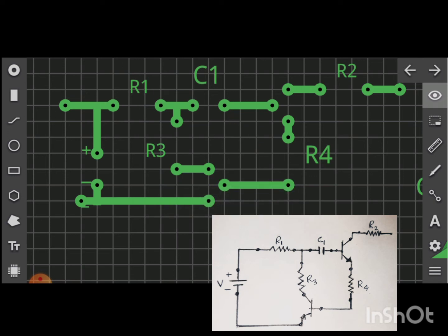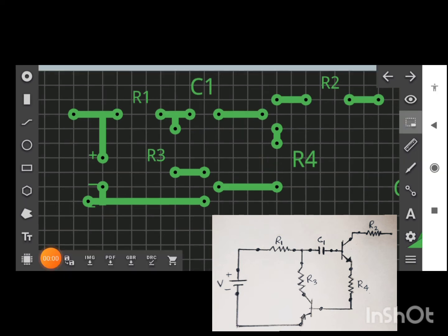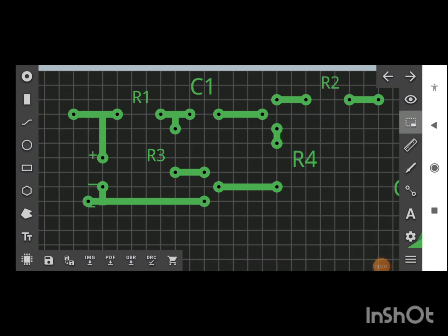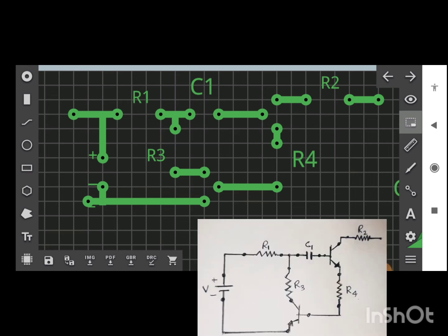Otherwise, practically we have completed your circuit. I hope you understood. Normally we take this, which is the front view, how it looks after mounting. But for printing on the circuit board, we normally take a print of the back view. We have to take the back view of this, which you can call a mirror image.